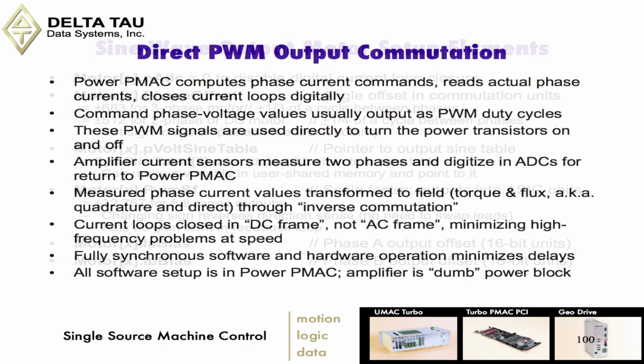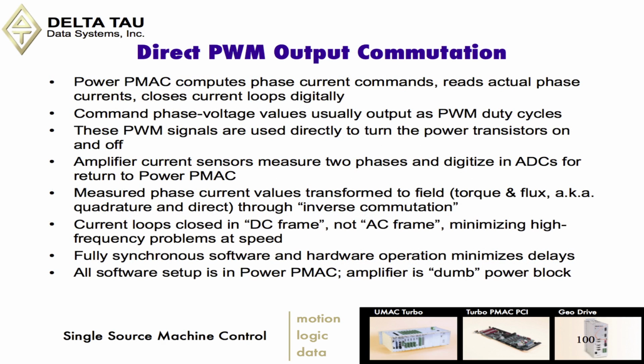Now with direct PWM command of motors in Power PMAC, Power PMAC is going to actually not only compute the phase currents, but it's going to read the actual phase currents back and then close the current loop digitally inside of Power PMAC.